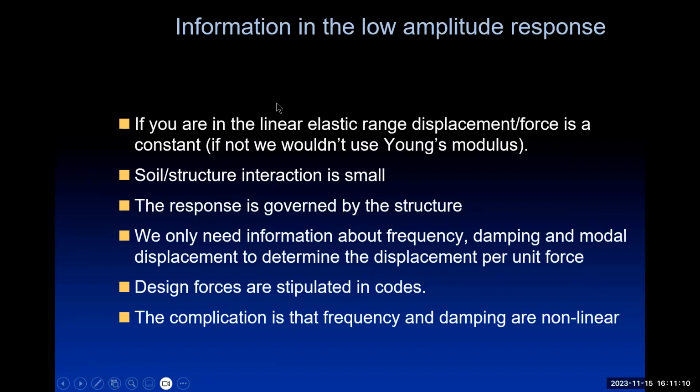So if you're in the linear elastic range, displacement per unit force is a constant. We use Young's modulus, and we wouldn't if we didn't think that displacement per unit force, stress strain if you like, in the very small, is Young's modulus. It is for entire structures as well, where we're looking at displacement per unit force.